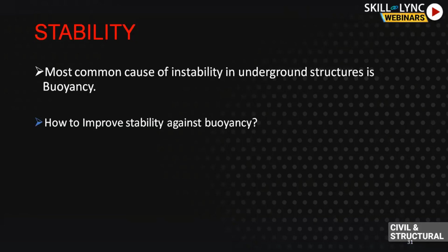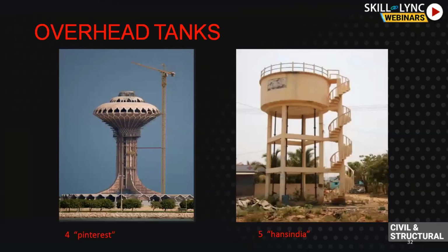So that if there is enough reinforcement, but the structure is uplifted, what is the use of the structure? All the hefty amount has been wasted. So the most important thing when you will be working on underground structures is stability, other than cracking. It should not uplift because of buoyancy effects. Now I'll go to a little introduction to elevated tanks.